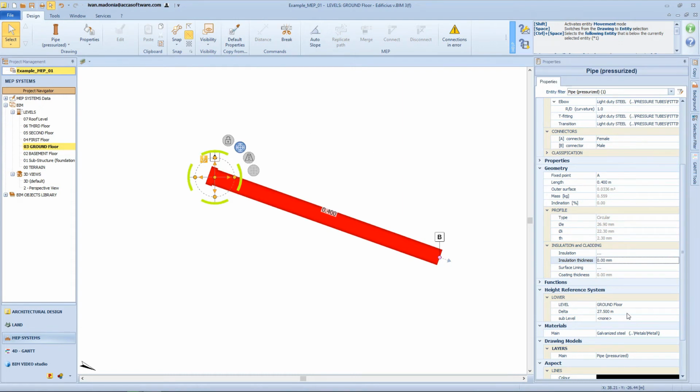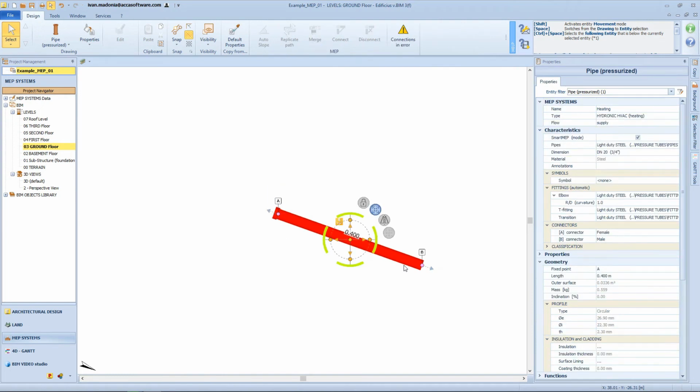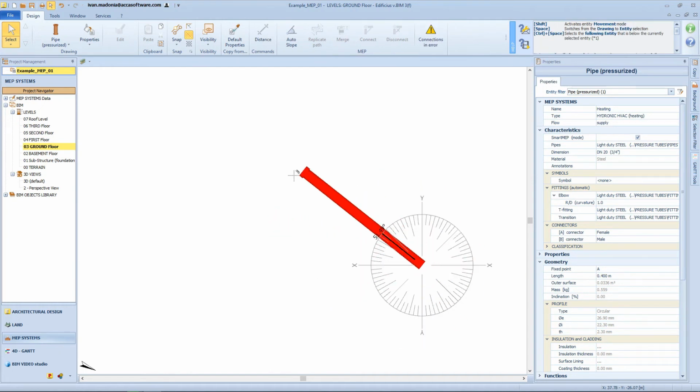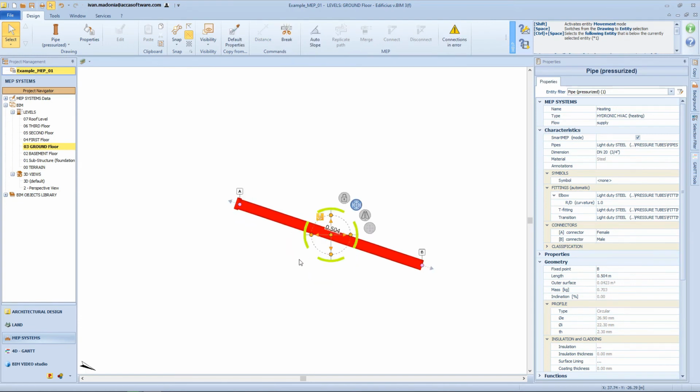Also, on the levels you can modify a pipe in the same way as in 3D but with the following limitations due to the representation in 2D. There is no green arrow to move a node vertically. If the pink circle is activated, the protractor appears to reshape the pipe. In correspondence with the object grip, the cube for identifying a different floor is not available, while all the other functions valid in 3D are active.